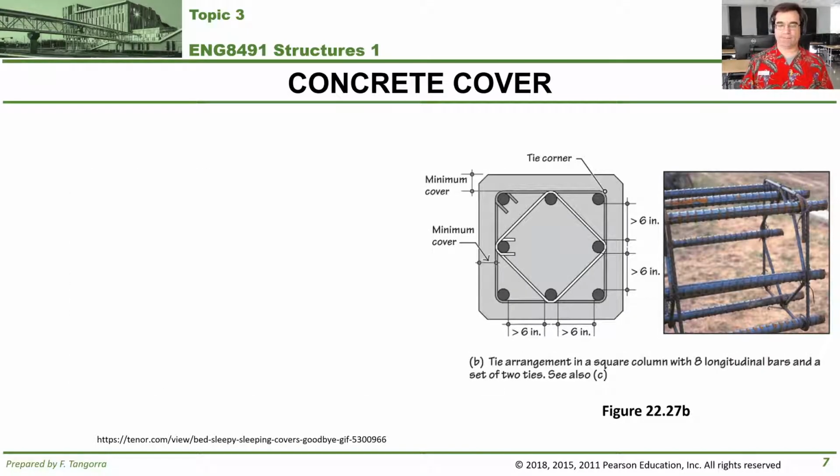So here's the thing. Concrete cover is the amount of concrete that you put on top of the outermost layer of reinforcing steel. So like right here. The idea is this. Reinforced concrete has to be exposed often to the elements. So that's rain, snow, wind, pooled water, salt maybe from ice prevention techniques.